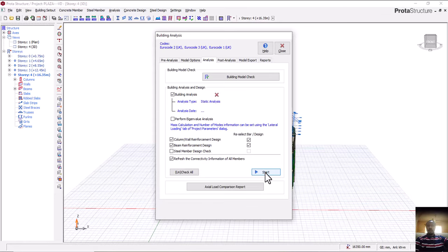So if you want to practice this, you can go ahead and analyze without clicking on those ones I've shown you on how to analyze your irregular structure using a semi-rigid. Design it based on what you have clicked, and also leave it as it was, and design and check it. You will still have the same result. Why? Because your structure is very small. But when you have a massive structure, definitely it has effect. Is that clear? All right.